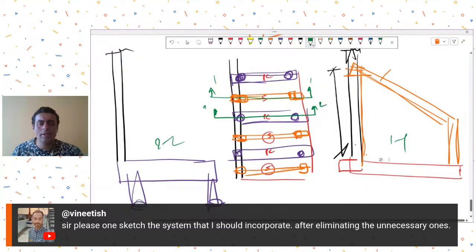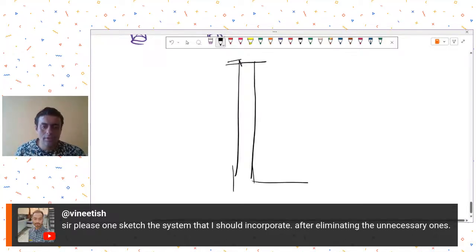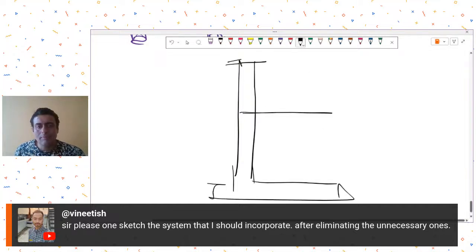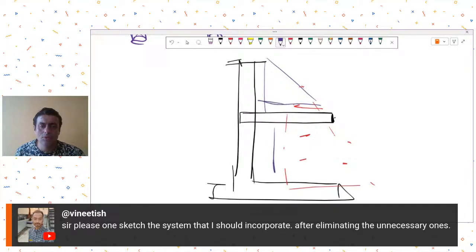There are researches, I mean people do it like this also, and there is a lot of research work that goes into this. Let's say you had a toe heel slab like this. What if I were to introduce a slab in between, like this? Instead of having an uplift pressure acting like this on the total wall, because of introducing this additional cantilever slab somewhere at mid height, it helps you break that soil pressure triangle into, let's say, two smaller triangles.